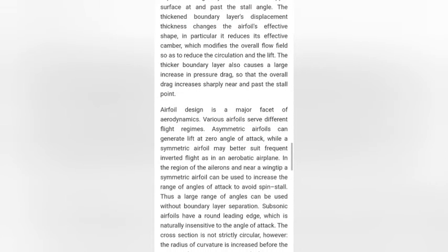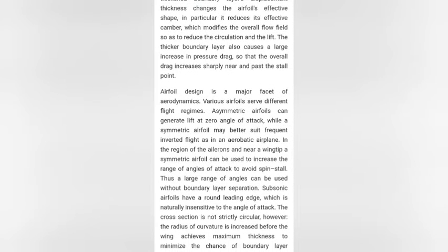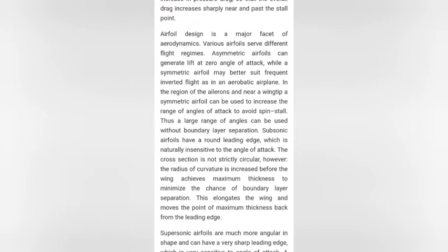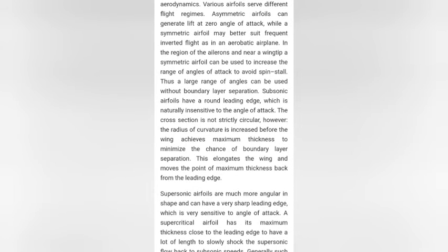Airfoil design is a major facet of aerodynamics. Various airfoils serve different flight regimes. Asymmetric airfoils can generate lift at zero angle of attack, while a symmetric airfoil may better suit frequent inverted flight, as in an aerobatic airplane. In the region of the ailerons and near a wingtip, a symmetric airfoil can be used to increase the range of angle of attack to avoid spin or stall. Thus, a large range of angles can be used without boundary layer separation.